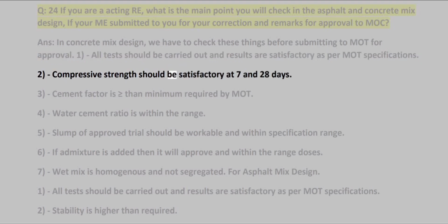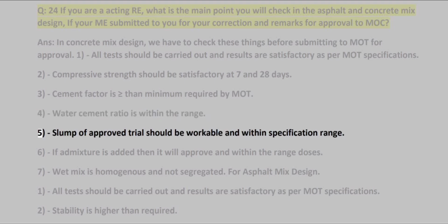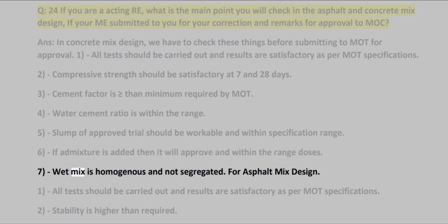Compressive strength should be satisfactory at 7 and 28 days. 3. Cement factor is greater than or equal to the minimum required by MOT. 4. Water cement ratio is within the range. 5. Slump of approved trial should be workable and within specification range. 6. If admixture is added then it will be approved and within the range of doses. 7. Wet mix is homogeneous and not segregated.